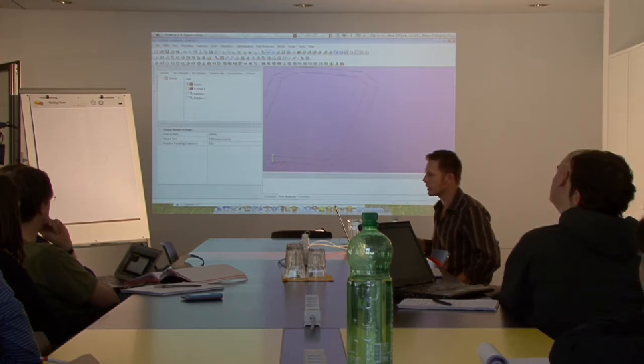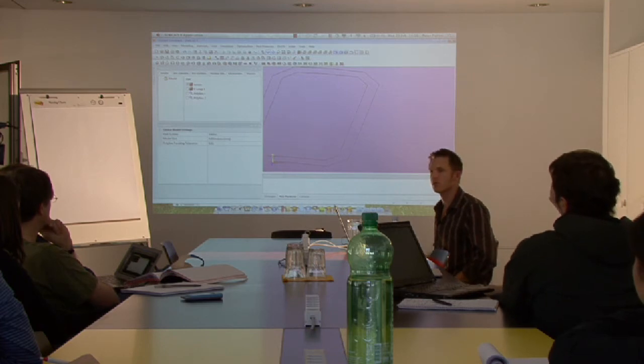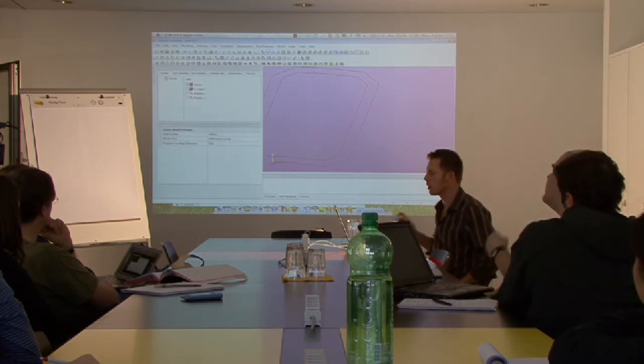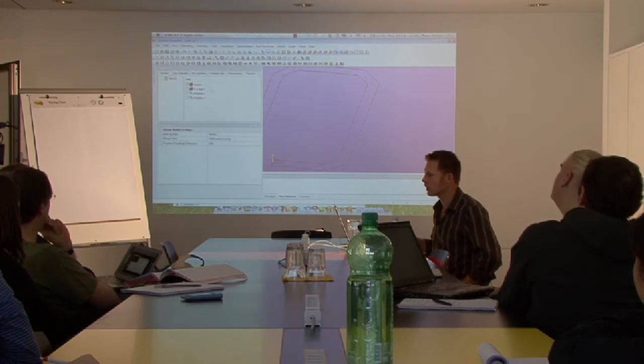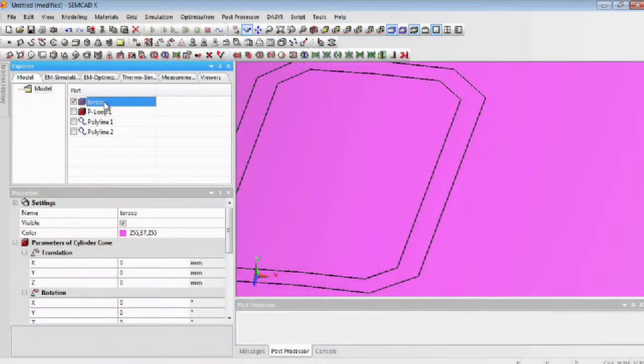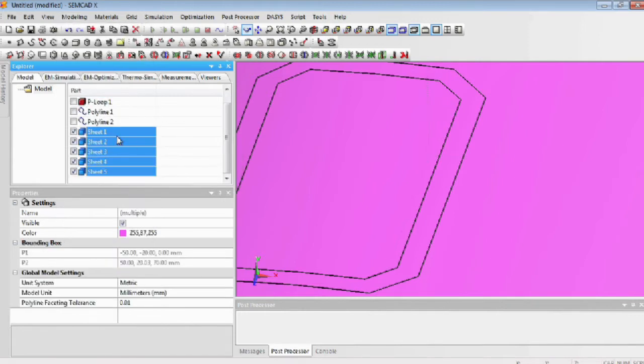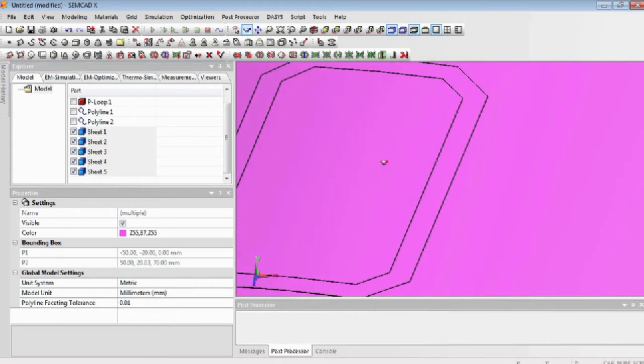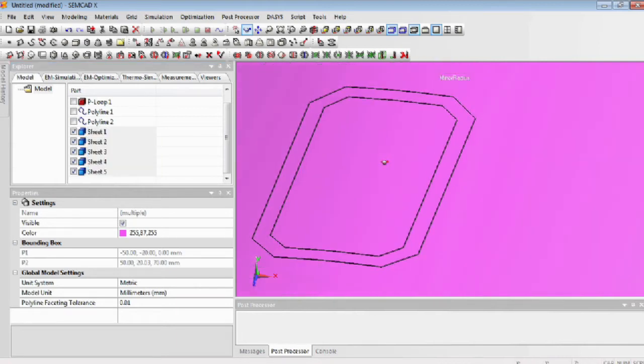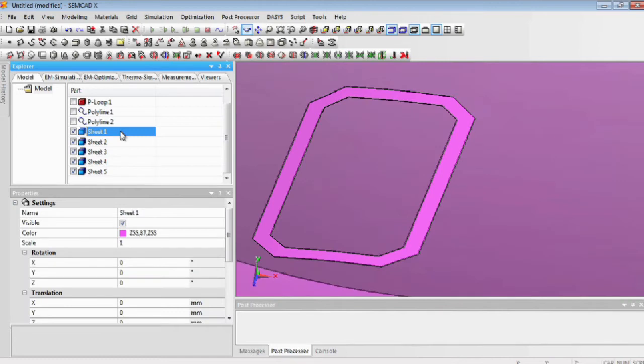What we want to do now is actually extract a surface in that plane so that we can actually model our antenna. So again, I'm just going to select the torso here, and under some of the sheet or surface tools that we have, you'll find the explode function, and that's just going to create basically a set of faces, and in this case the first one is actually the surface of the antenna.